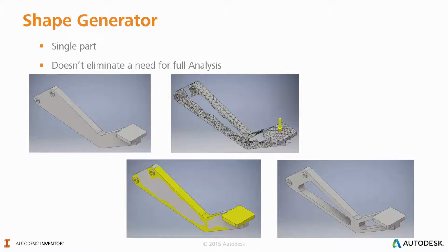So if we look at this process here, you can see that we analyze a generic part that we've designed. The system will come back and highlight areas, or a more idealized shape of our part, in areas where material may not be required. We then use that as a guide to replicate that in our actual CAD geometry. And then as a final process, we would run off and analyze that design before potentially having it assessed by independent assessors and then tested under real world conditions.